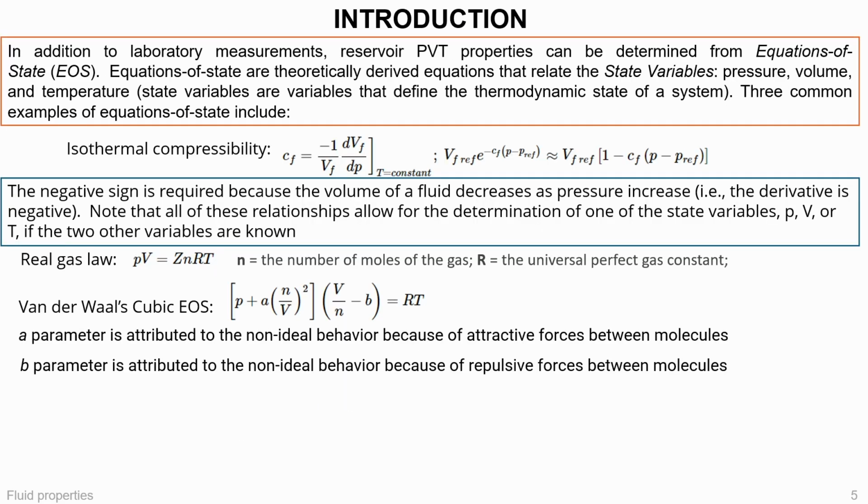This slide shows a typical PVT analysis system and reminds us that PVT measurements are done with specialized high-pressure equipment. A PVT cell is basically a high-pressure vessel that allows engineers to control pressure and temperature while measuring the fluid volume and phase behavior.